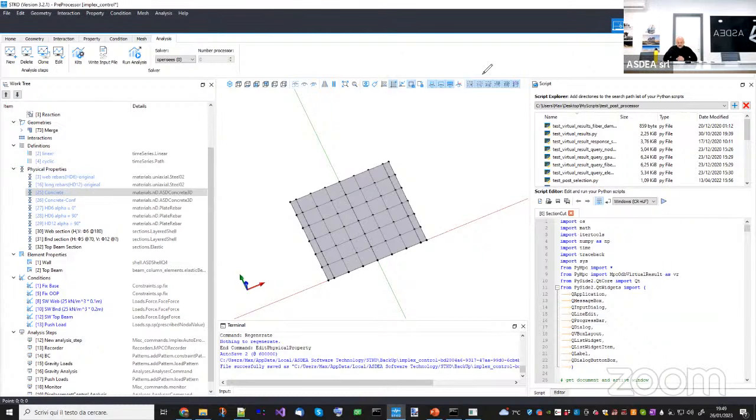Because what was happening before, as I said, since the material model was damaging too fast before, I had to pay a lot of attention to the boundary condition, simply because the material was a lot more unstable under those conditions, okay? Now the material is so stable that even if you put a slightly different boundary condition there, it is not going to change a lot, okay?